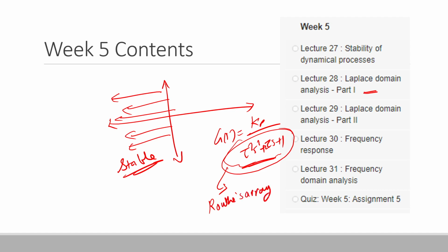So over here also we'll be using the Laplace domain. In these two we'll be just using direct substitution and the Routh array to analyze the stability. Then we will study systems where we have an exponential term, let's say e^(-τds). Then the conventional approaches related to the Routh array won't be possible, because basically we need to find the roots of this equation.